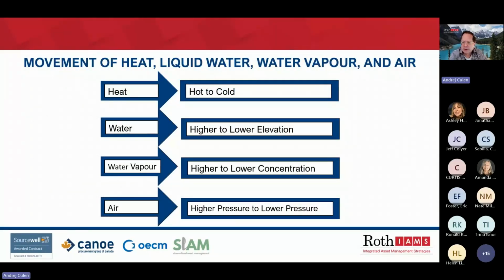The main purpose when we think of a building envelope layer is often thought of in energy terms, to act as a thermal barrier. There are several different flows or environmental movements which the envelope barrier protects us from. Our knowledge and understanding from science has accelerated at a very fast rate to predict and design protective membranes around our buildings. The environmental conditions we need to protect against are heat, liquid water, water vapor, and air movement.